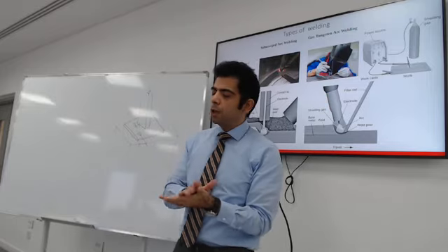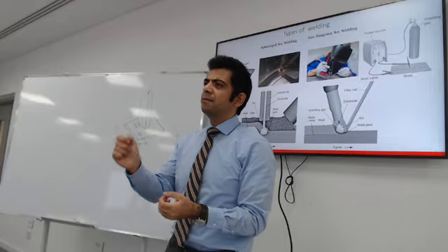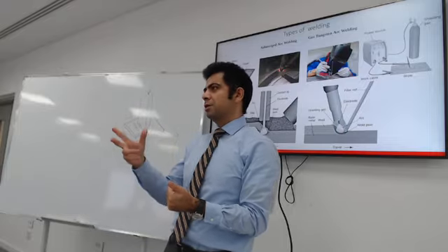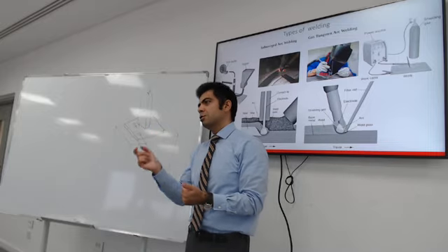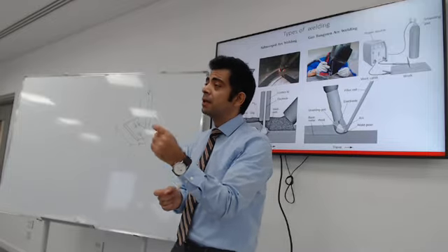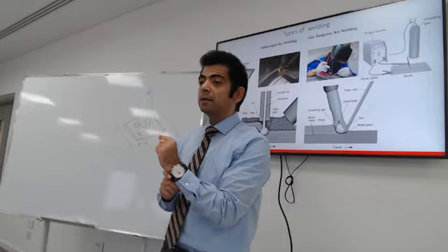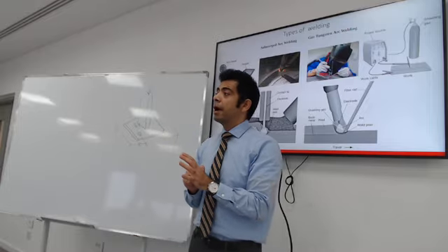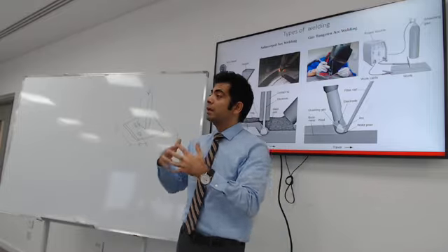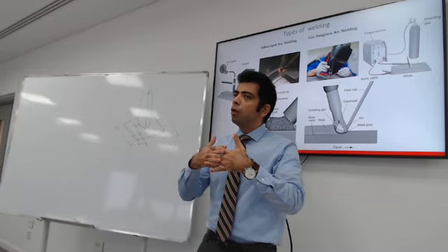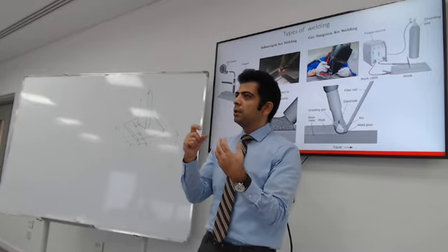So what I want you to know is when you're specifying weld, so you're the structural engineer, you're producing structural drawings, you need to spec some properties of weld, at least to take it into account in design. So when you're designing a welded section, you need to know what kind of electrode they're going to be using.